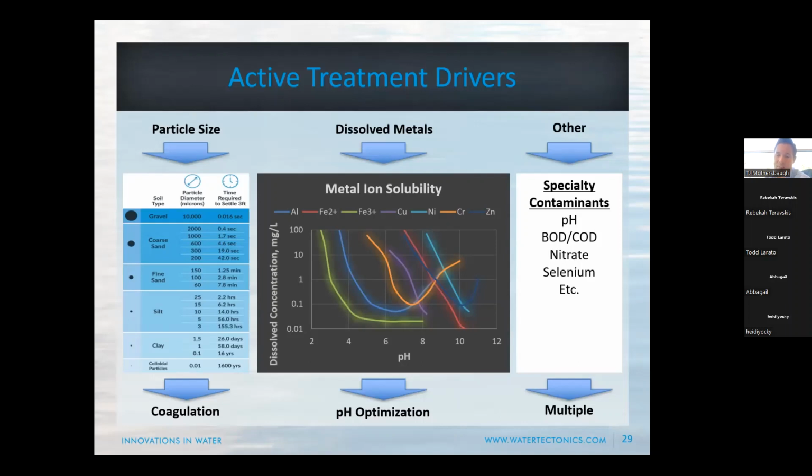And then as I raise the pH, that zinc is going to react with the excess hydroxides, right? The OH groups that are in the water because of that higher pH. And less of that zinc is going to be able to stay in that soluble form. It's going to react with those hydroxides until you get down to a pH of like 9.5, 10. And now only 0.1 part per million of zinc can stay within. And the rest is going to precipitate out as zinc hydroxide, which you'll be able to see and grab onto and coagulate and filter, right?